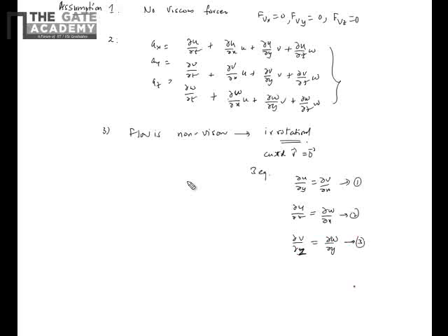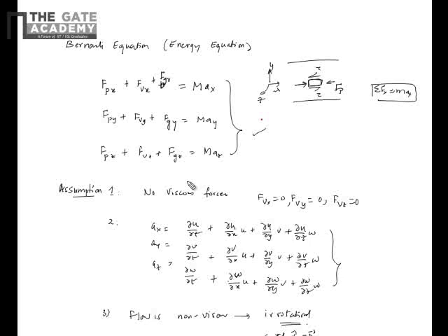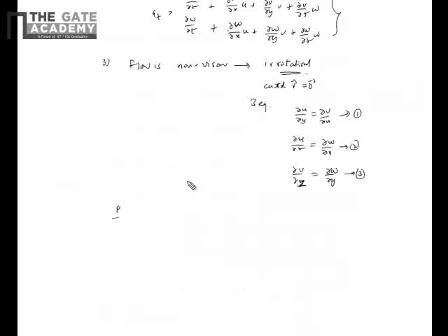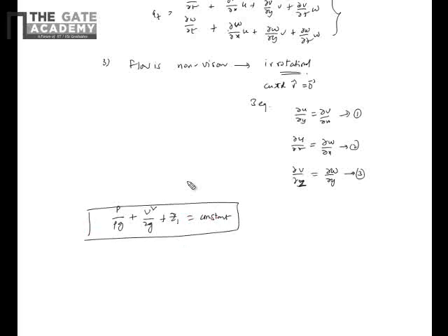So if you substitute all these three combined in this Newton's law, you get something called this equation: p/ρg plus v²/2g plus height z is equal to constant. So this is a general equation. This says that this quantity will remain constant at any 2 points in the flow. This quantity will be constant. So here v is the total velocity, I'm taking all the components.